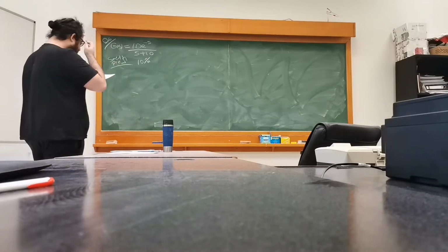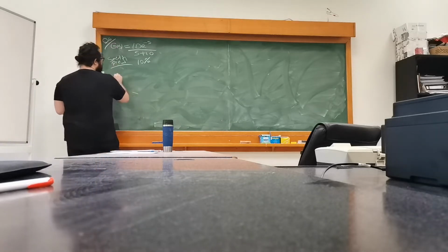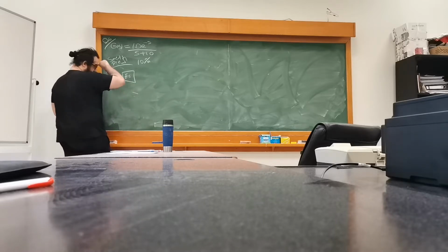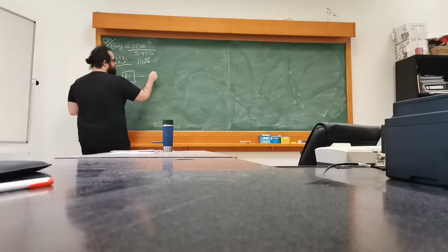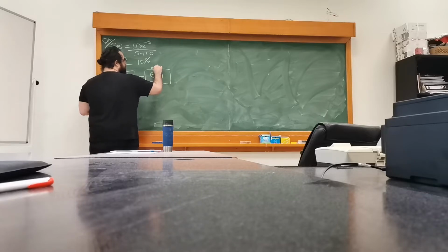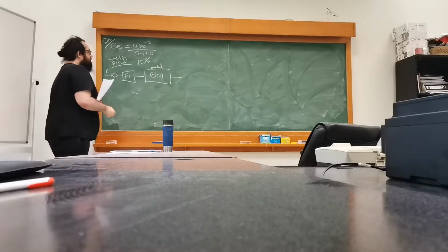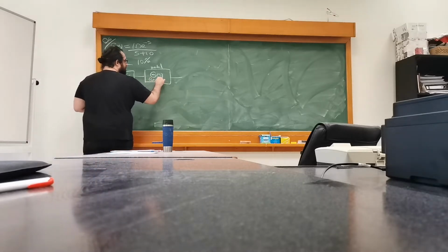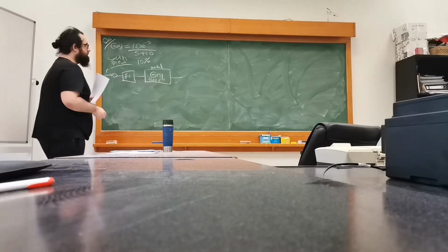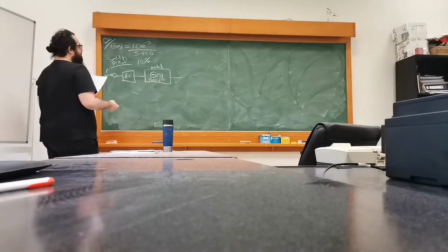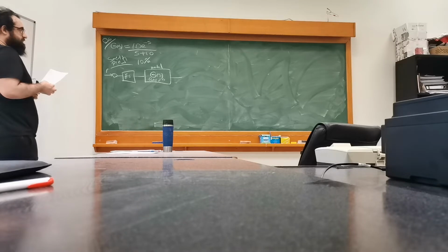Now, what is the Smith predictor? How do we use it? Let's start with that. We will have a certain controller. We will have our feedback structure that we always use. But then there is this system, the model. I'm going to call this model. It will have basically a G0(s) and some delay in it. So I know what the mathematical model is. This is the minimum phase part, and then we will have also a certain delay part.